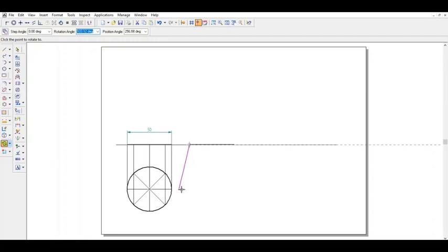Direct problems will be based on something like, this point is touching VP, this point is touching HP. Let us say it is resting on A, with points A, B, C, D, E. So point E is opposite to point A. He may give it in the question that the point opposite to the point on which it is resting, that is point A, will be touching VP or something like that.